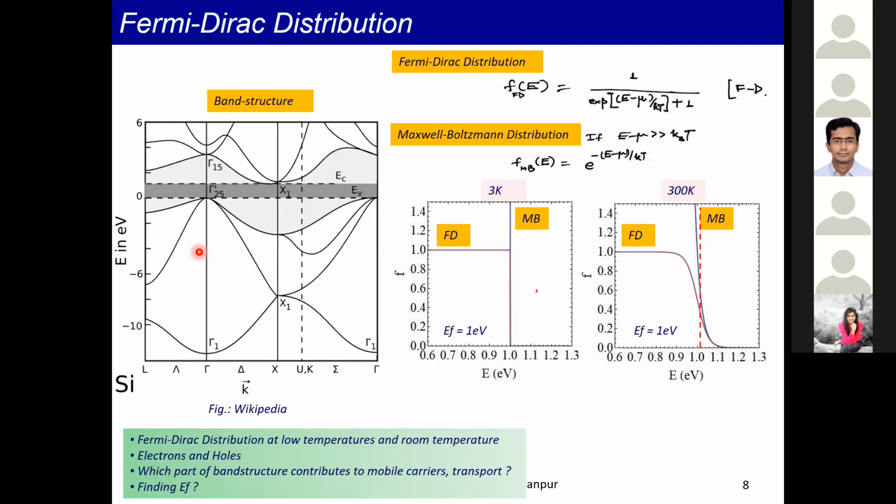I'll talk about heterostructures when I talk about band diagrams. Essentially, hBN will have its band structure and graphene or whatever other material will have its own band structure. Now, as you go from one material to the other, the conduction band changes. This spatial variation of the conduction band is what is known as a band diagram. I'll come to that. That is what you worry about. There you don't worry about band structure, but you worry about band diagrams when you are spatially changing things.